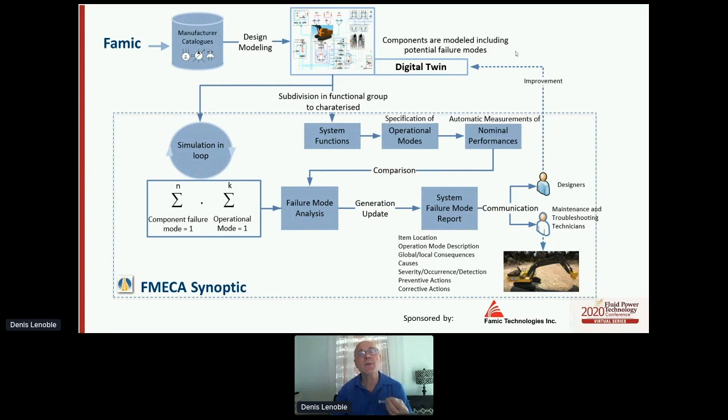When I was talking about internal leak in a cylinder, for example, we are able in Automation Studio, in a cylinder, to declare, not activate, but declare this internal leak could exist. This external leak at port A could exist. The external leak at port B, and so on. With other parameters, for all components, there are some specific failures that can be declared also. So the concept is the following one.